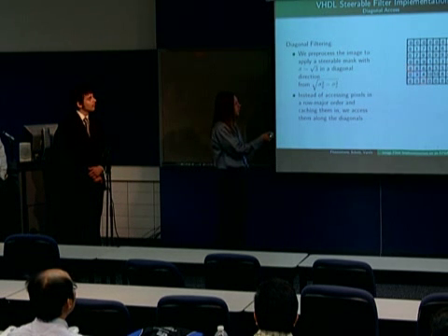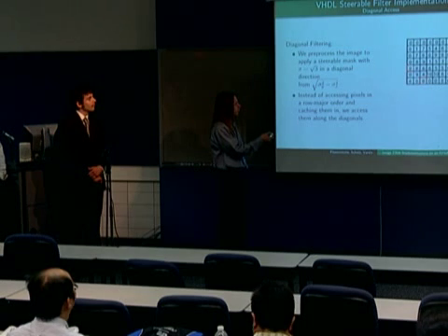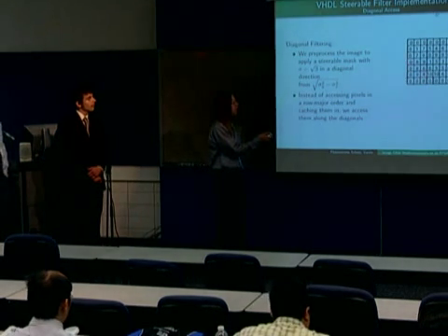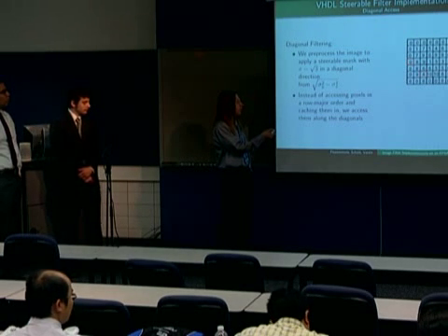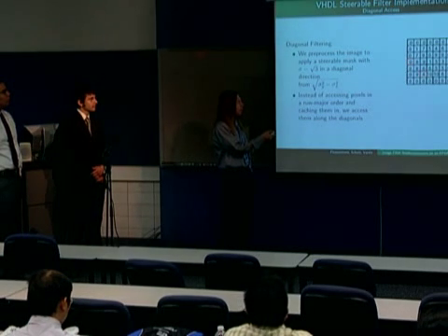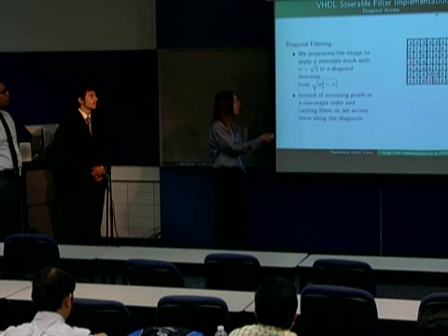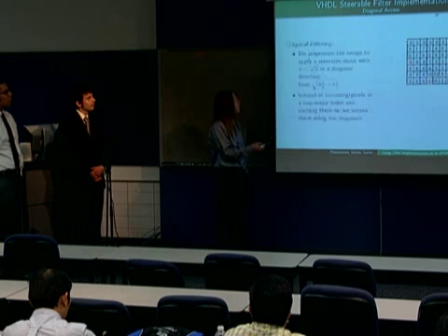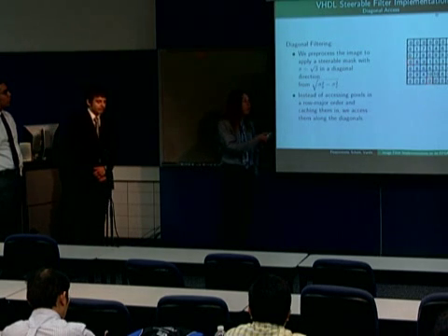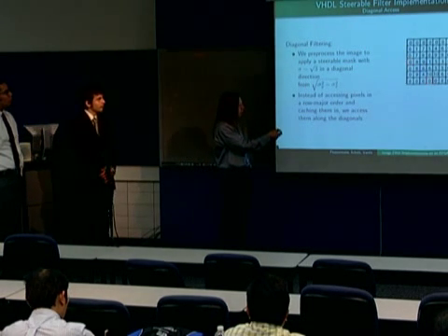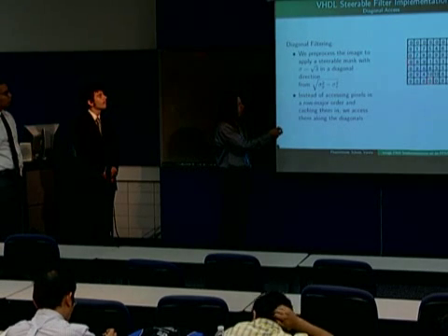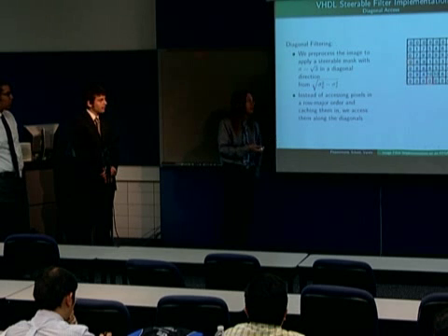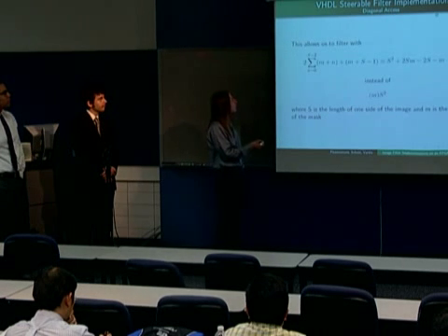So as you can see, it reads this pixel and these 2 0 pads, and it's convolving this pixel. Then it gets to the next row, and it reads these 3 pixels to convolve this one. And then it gets to the next pixel, and it uses this one. And so while you're not getting good efficiency in that diagonal, as you get towards the biggest diagonal, you're gaining a lot more pixels per thing.